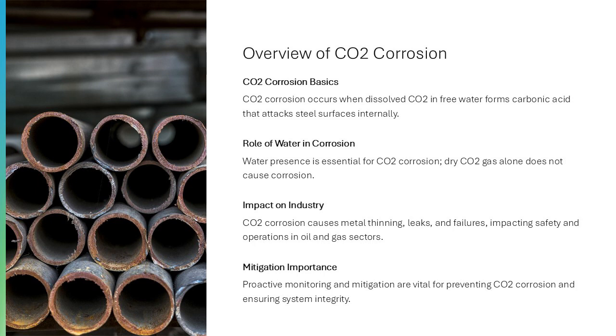attacks steel surfaces. Unlike dry CO2 gas, which is non-corrosive, the presence of water is essential for corrosion to occur. This phenomenon is prevalent in systems where condensation forms due to temperature drops below the dew point, creating localized areas of free water. The resulting corrosion can lead to thinning of metal walls, leaks, and catastrophic failures if not properly managed. Understanding CO2 corrosion is vital for maintaining system integrity, reducing downtime, and ensuring operational safety.